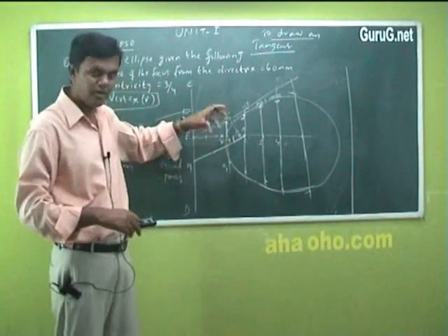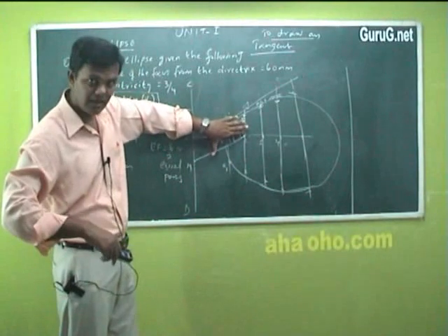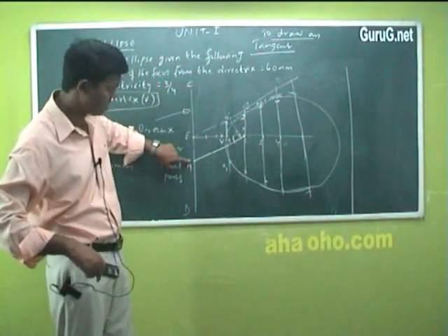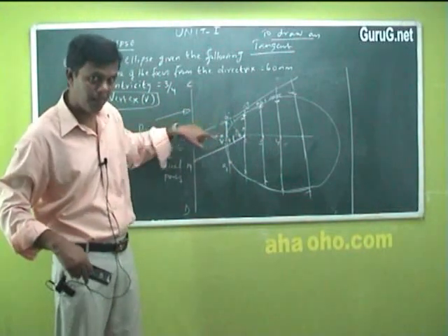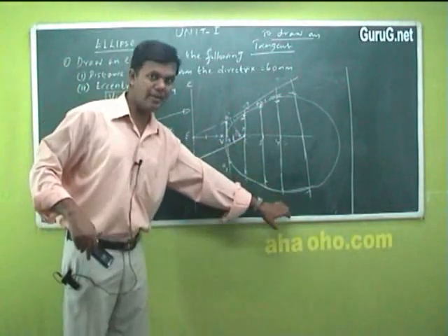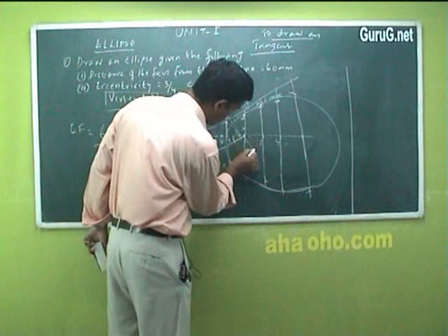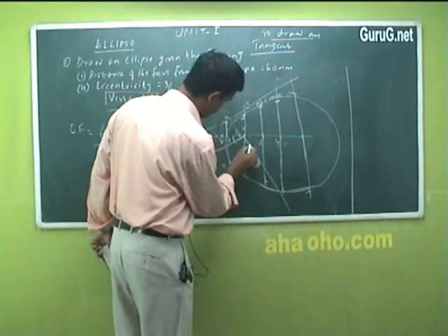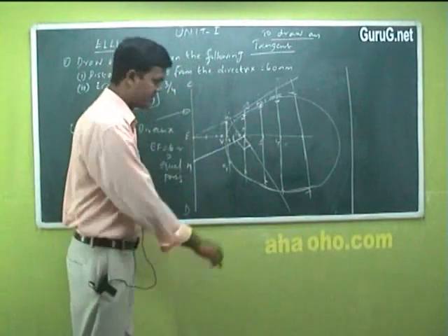That means you move your mini drafter and fix it here after drawing the 45-degree line which joins at this point, say suppose FM. From this you fix one scale of the drafter. The opposite scale will be exactly 90 degrees apart, is it not? So you draw that 90-degree line down. Is it clear?